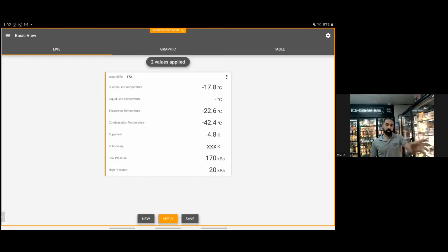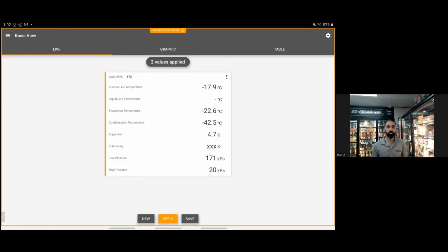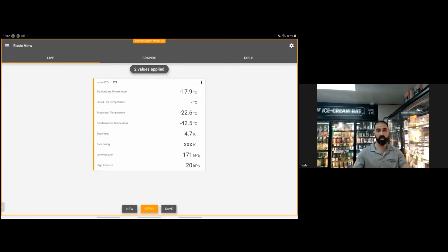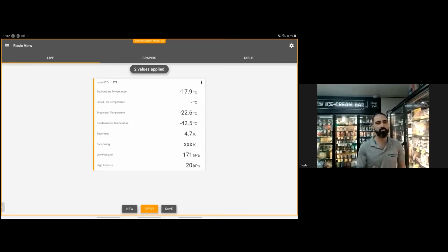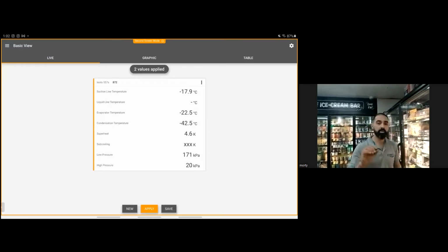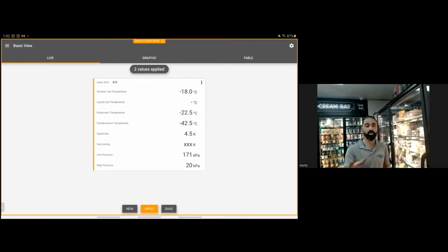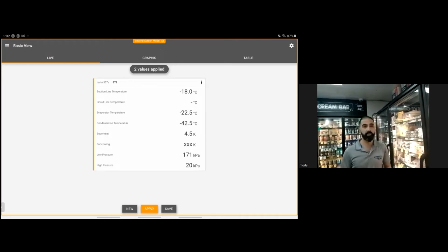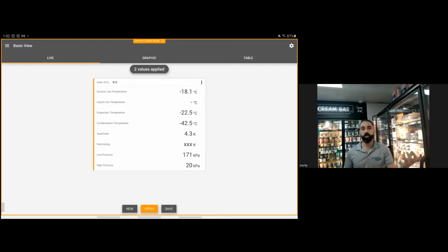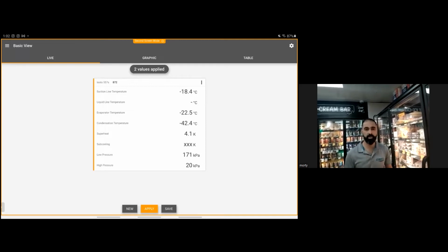When I connected my gauge outside, the first thing I paid attention to was my system superheat. It was beyond the envelope of the design condition, about 23, 24 thereabouts, and it started climbing, and I knew I was in trouble. So the first thing I did was check the discharge temperature. It was 112 degrees. At that point, I knew I had to back it off completely. So quickly, I went to my wholesaler, grabbed the capillary, sized it up, fitted liquid injection, and lowered my superheat at the compressor inlet.